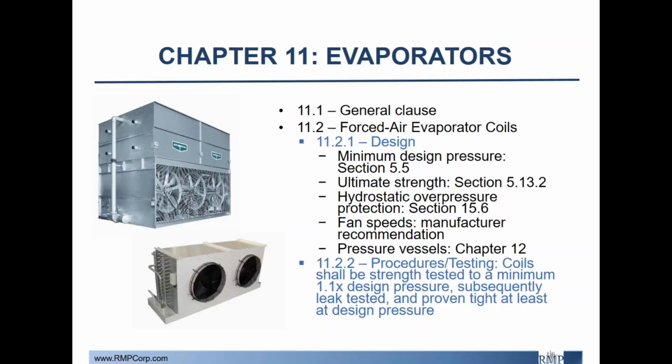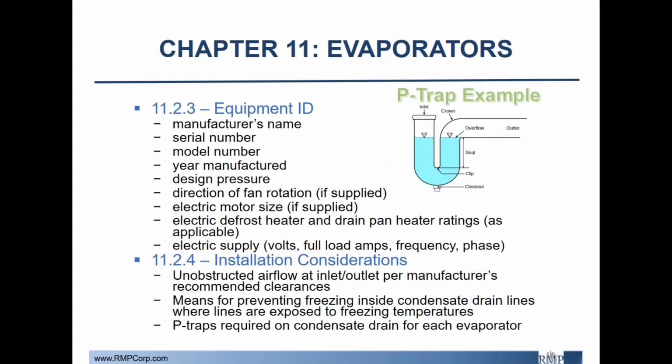Oh, actually I forgot one note too. In terms of hydrostatic overpressure protection, in general, it's required where refrigerant coil inlet and outlet connections can be automatically isolated. And again, that'll be something a little repetitive for each type of evaporator, but in general, we'll cover a little bit different aspect of that.